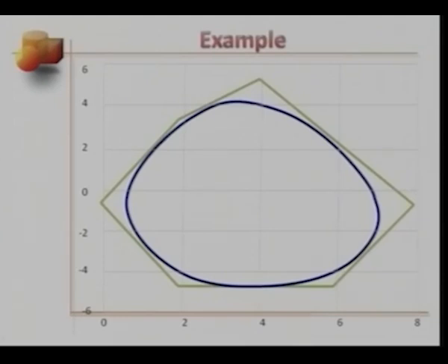I would want you to do this exercise with me. Okay, so let's come back. We had 12 design points. The order of this closed B-spline curve is 4. So we should have 12 plus 4, which is 16 knots in all. This closed spline is the result when we specify Ti equals I for I going from 0 to 15. So if you notice, these are 16 equally spaced knots.